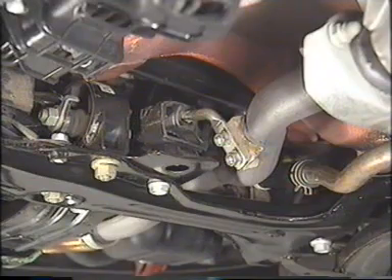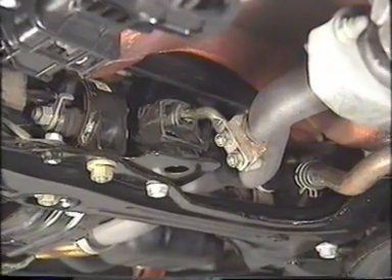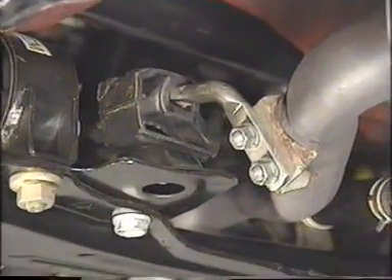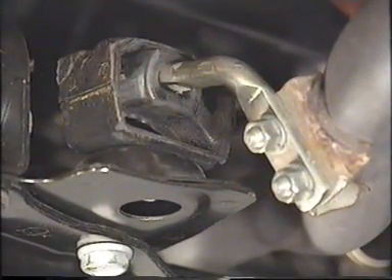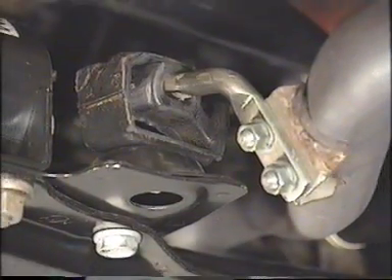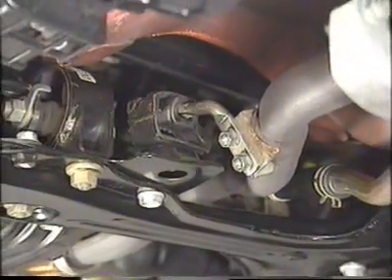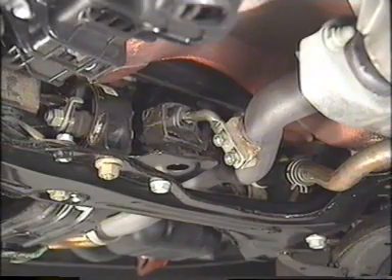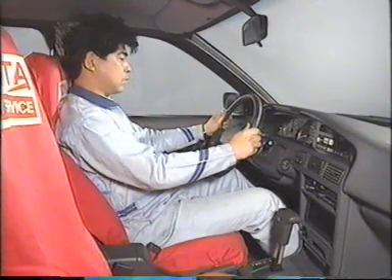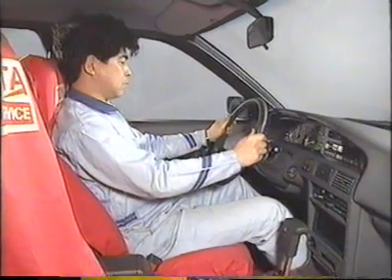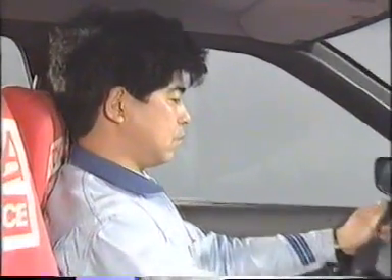The vibration of the exhaust pipe is transmitted to the body if the exhaust pipe support is not fitted correctly. The body begins to vibrate, causing the air to vibrate also. This vibration is heard in the form of sound or booming by the driver.